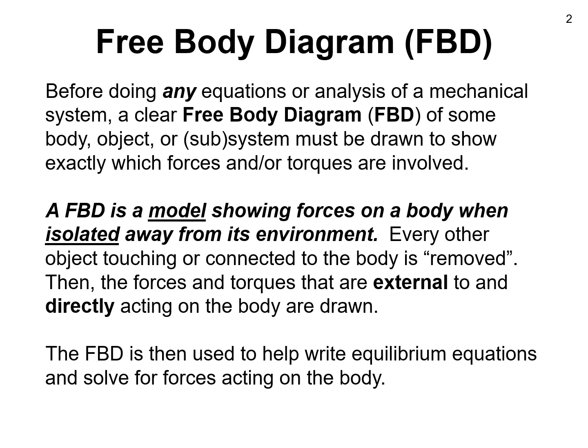A free body diagram is a model showing forces on a body when isolated away from its environment. Every other object touching or connected to the body is somehow removed. Then the forces and torques that are external to and directly acting on that body are drawn. The free body diagram is then used to help write, for example, equilibrium equations and solve for forces that are